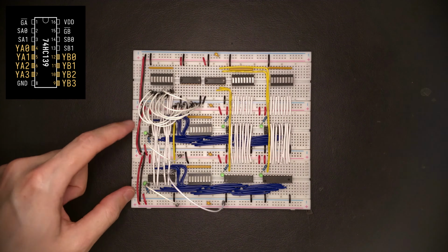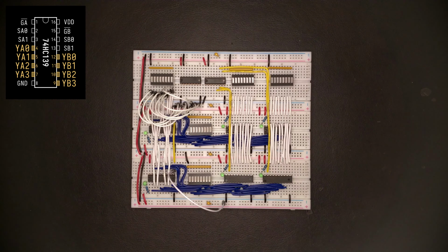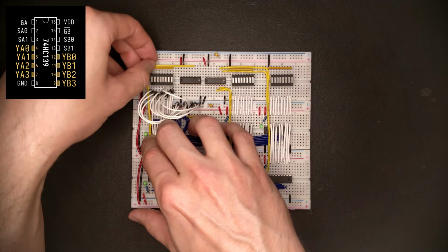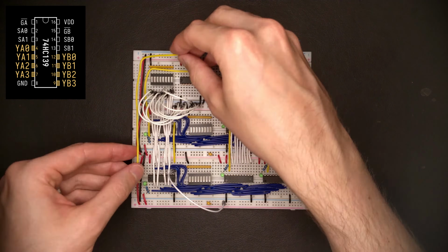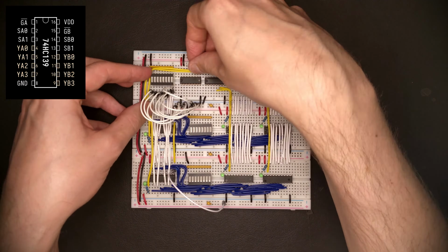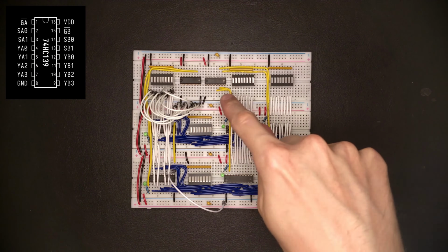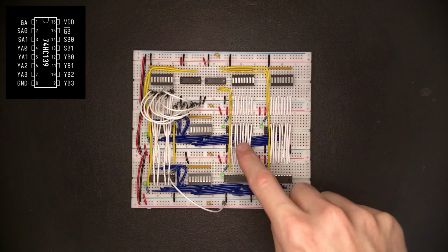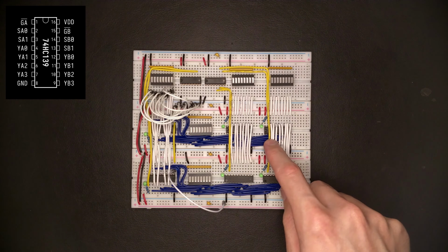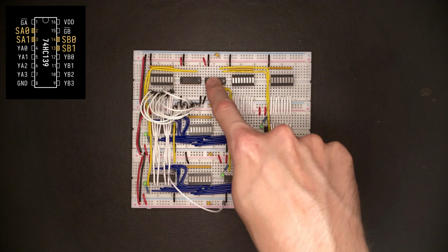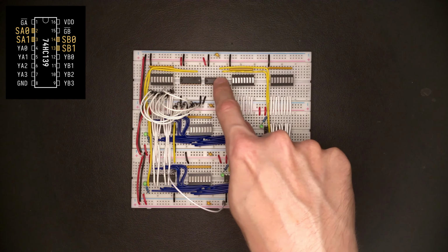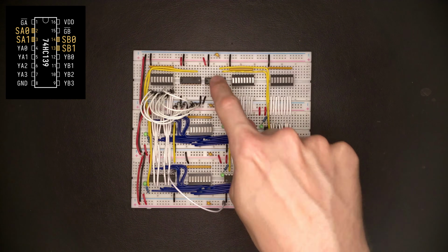And the same for the clock enables over here. And now, instead of fiddling with these individual strobe wires, where we have this constraint that only one of them ever can be active, we have a much more convenient input here of 2 bits for a 2-bit binary number, which picks which one of the 4 outputs is active. So let's wire this up.